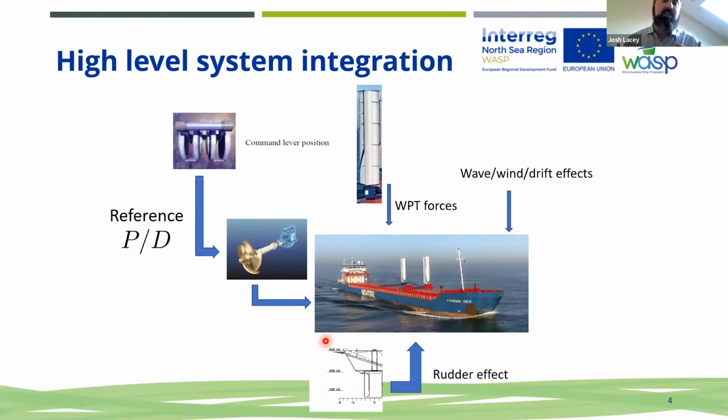And then if we step back even further to look at the digital twin from a high level, we get to the stage where we have all of the layers put together. We have this dynamical model of the ship, the hydrodynamic perspective of how the ship is traveling in water, what the hull resistance is, and so on. We incorporate the impacts, if any, from the rudder, the connection of the propeller to the main propulsion system, what sorts of losses occur there, and also what sorts of control may occur. In this particular application, this ship has a propeller with variable pitch. So how that may come into play when we're using a wind propulsion unit is included in the model. Obviously the wind propulsion unit itself comes into the digital twin, and this capability, again, to control and actuate the controller for the propeller.